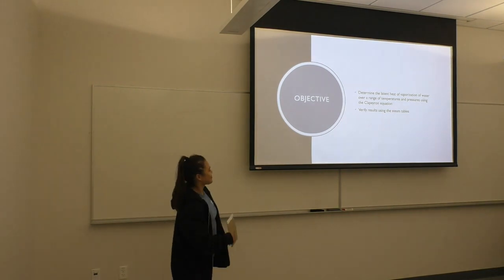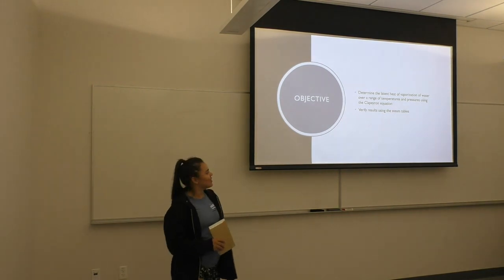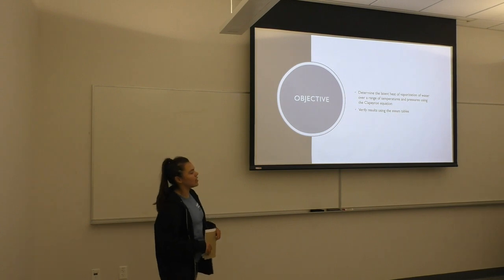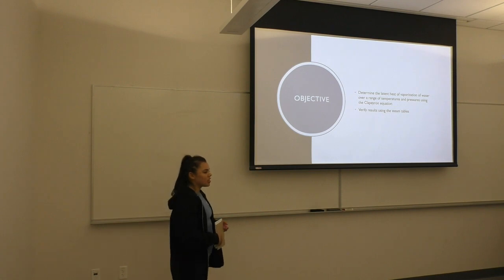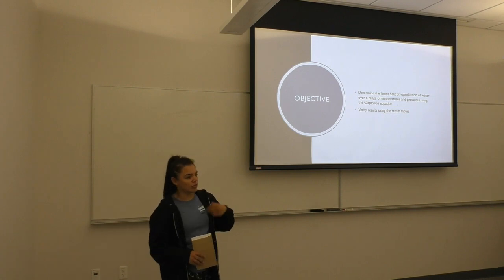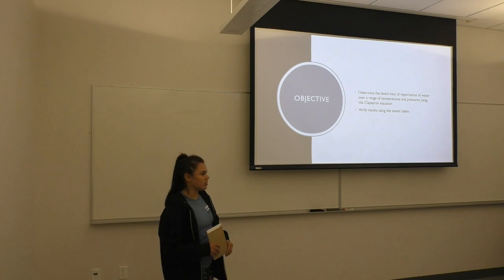Okay. The objective of our experiment is to determine the latent heat of vaporization of water over a different range of temperatures and pressures using the Clapeyron equation, and then also verify the results that we get using the thermo steam tables.